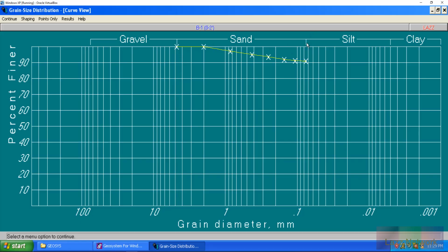And as you can see right here, you got little tick lines, which technically go all the way down to the bottom. And here's the thing. With our number 4, like I've been talking about for a while, your number 4 is your final separator for it going into sands. You have gravel going up all the way to 100 millimeters, or greater if you have anything greater than 100 millimeters. Your gravel is anything greater than your number 4 sieve.